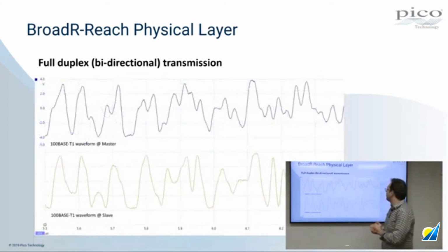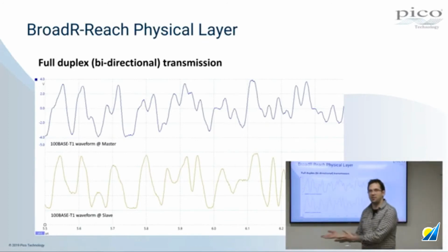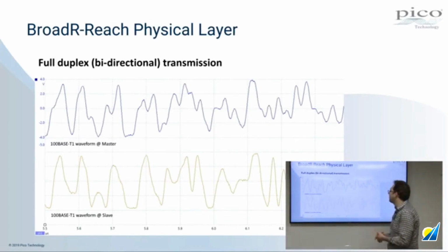The unidirectional components of this PAM3 signal from each transceiver to the other are going to interfere across the channel, and you're actually going to end up with a waveform that looks a bit like this if you probe somewhere along the channel. This presents a challenge because if you are a transceiver on the channel, you know your own contribution to this signal, and you can subtract it and infer what the other party is trying to tell you.